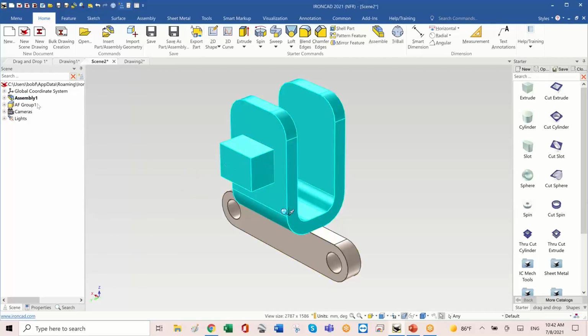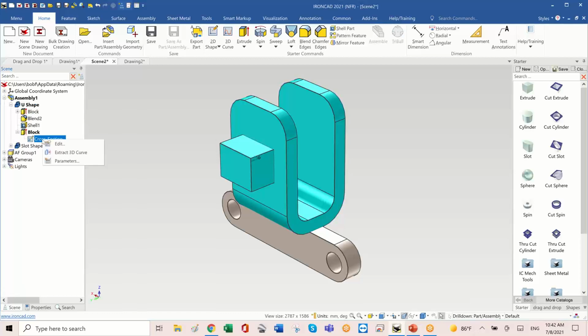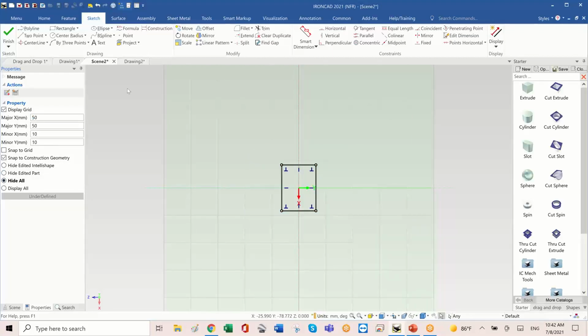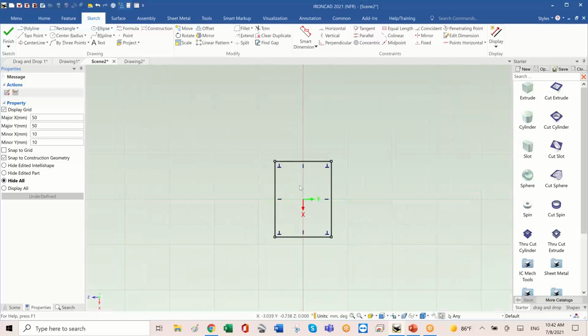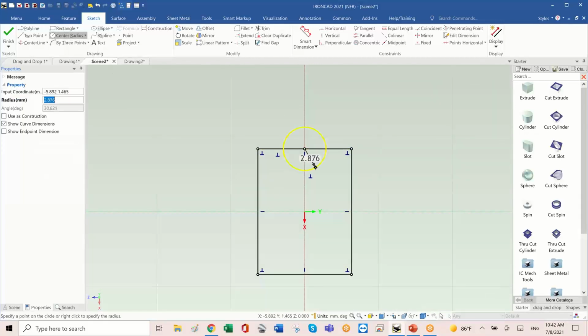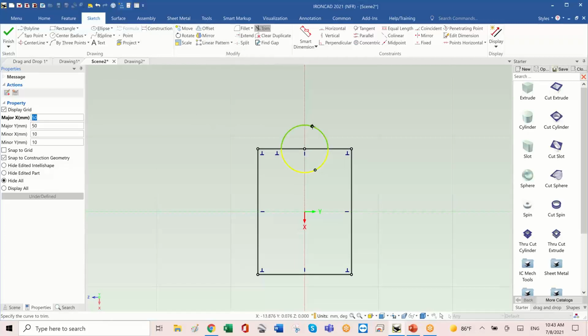But you know what? This right here, I want to look at that and say, what was that thing that I just added? Oh, I just dropped a block, but what was it created of? Oh, that block actually has a sketch. What does that mean? That means that if I really wanted to, I could come in here and change this sketch. Trim away this, trim away this.